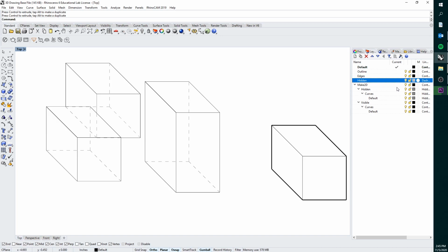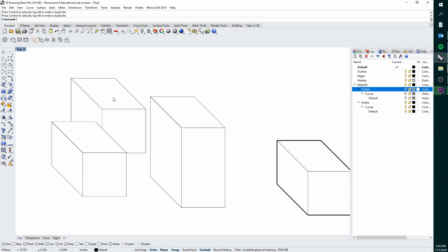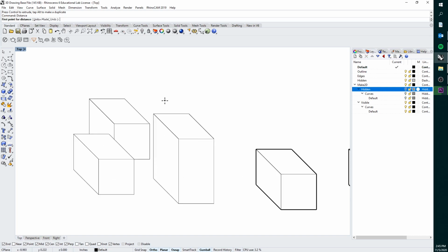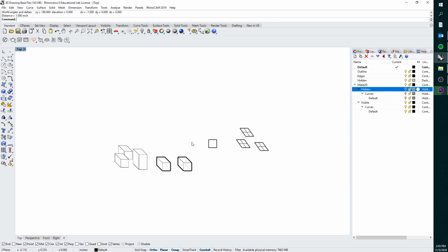So here what we can do is if we didn't want to see our hidden lines, we can get rid of those. And then this would be a true, again, measurable elevation oblique. So if we click from there to there, we see it's an inch. Again, I scaled that vertically, but these dimensions will totally be an inch. And then you see that all of our elevational data is still the same.